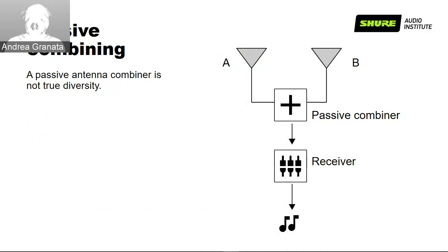This is something else you can take into consideration that will help prevent a complete dropout due to reflections. But still, as you saw in the graphic, which was pretty accurate, you can see a reduction of the quantity of signal reaching your antennas. That's pretty significant. So the first way to react to this multipath interference is to place two antennas at the receiver, have a pure and simple passive combiner, and then have this combined signal go into a receiver.